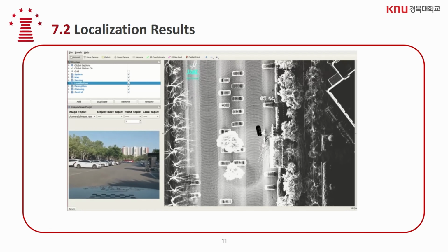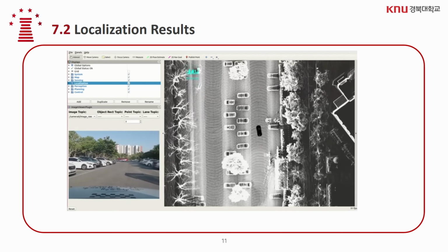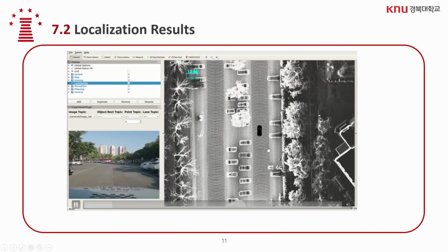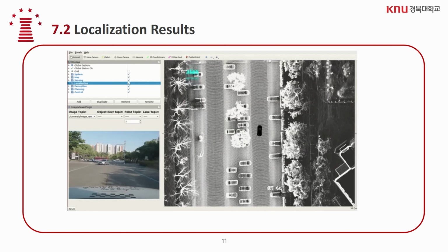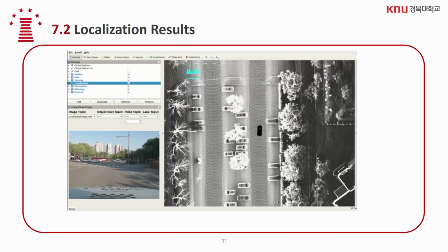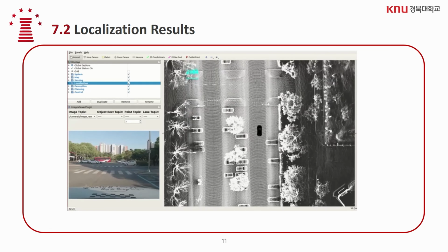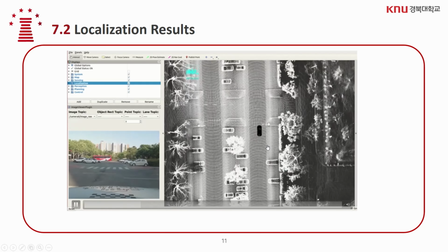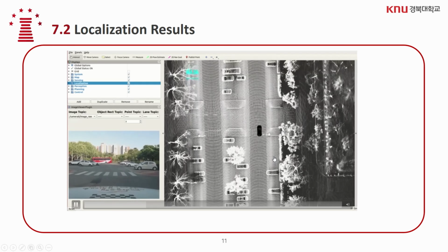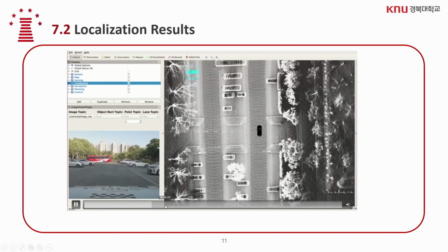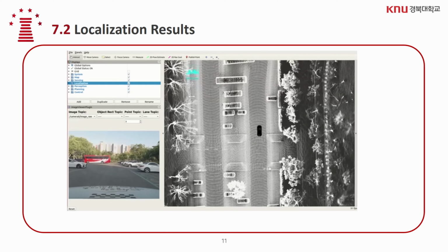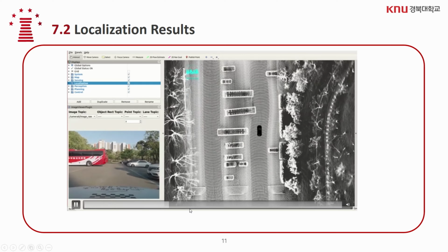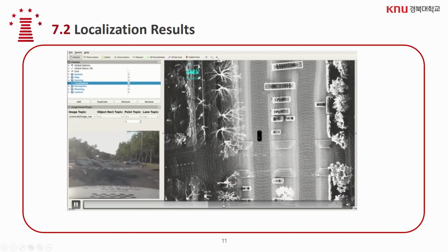So in the student parking lot, we did our experiment, and we are tracking the vehicle position. So there are so many challenges we need to address, but currently there is around 20 to 30 milliseconds of processing delay on the server side. But still, the system works reasonably, with around 20 to 30 centimeters of localization accuracy. So our goal was to do self-driving in automatic car parking. So the student parking lot was our experiment area. Then we were locating the vehicle position.